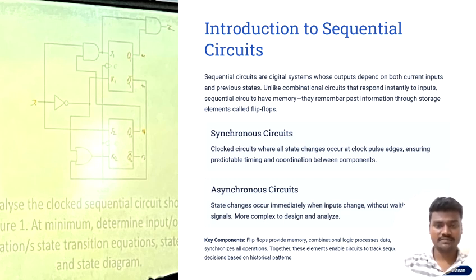What is sequence detection? Sequence detection is a digital circuit that monitors a stream of bits and gives a high output when a specific pattern is detected. Example: 1011, 110 and 101. This circuit is widely used in digital communication, data frames, information, and error detection, correction, and recognition.